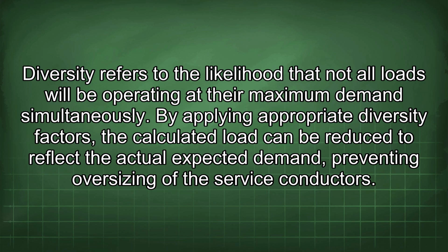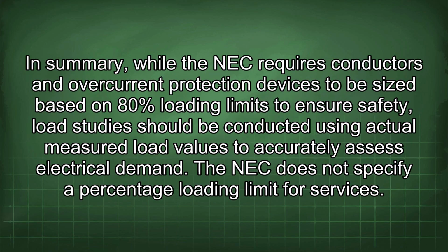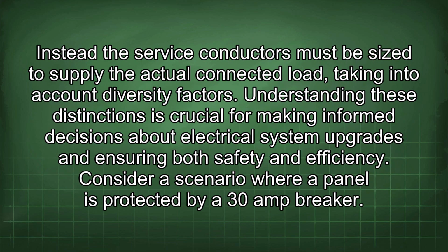In summary, while the NEC requires conductors and overcurrent protection devices to be sized based on 80% loading limits to ensure safety, load studies should be conducted using actual measured load values to accurately assess electrical demand. The NEC does not specify a percentage loading limit for services. Instead, the service conductors must be sized to supply the actual connected load, taking into account diversity factors. Understanding these distinctions is crucial for making informed decisions about electrical system upgrades and ensuring both safety and efficiency.